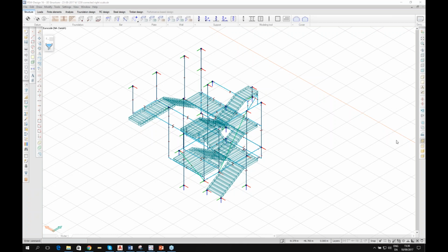There's a question here from Carl. Merge objects distance, how does that impact the meshing? Honestly, I'm not sure about this. I'll have to investigate it. I always recommend that this merge object is not used because it's difficult to control how it's adjusted. The new function in 17 will be much, much better. So normally I tell people don't use this auto merge. If you have mesh problems, go in and have a look and adjust the model manually so you know the model is correct.